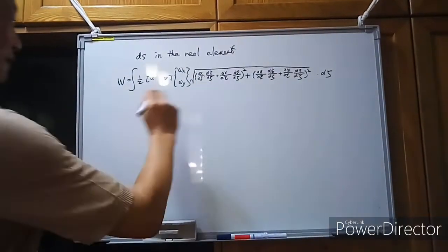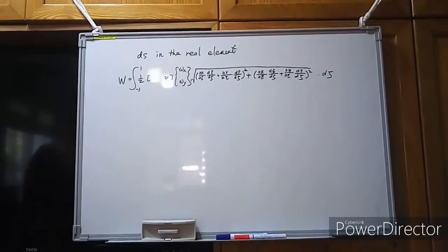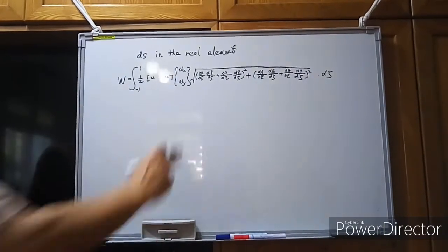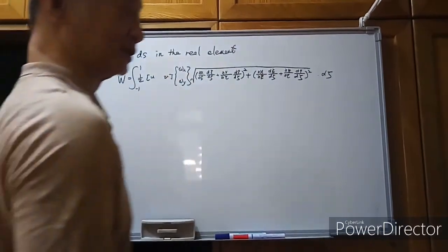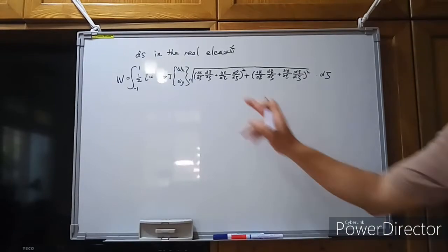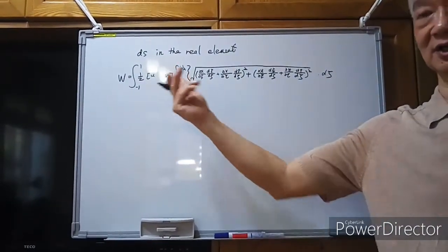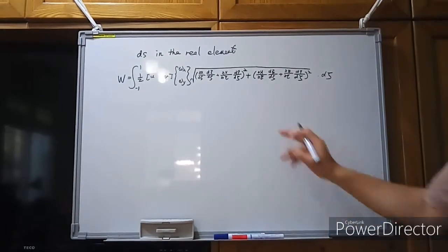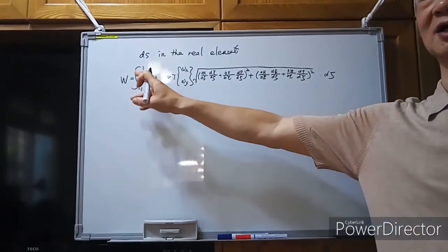And the zeta will be from -1 to +1. And if we know the zeta, then we can calculate the corresponding coefficient eta. And if we know the coefficient eta, then we can calculate the u and the v values. And we know we don't need to do the integrations.